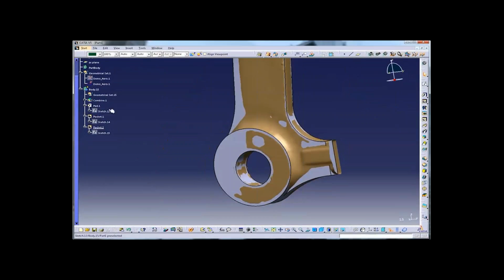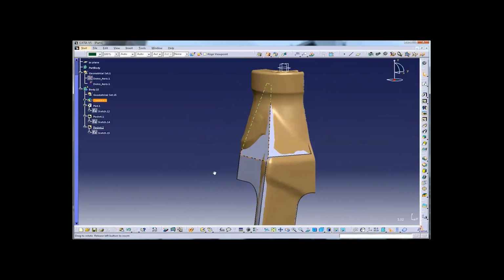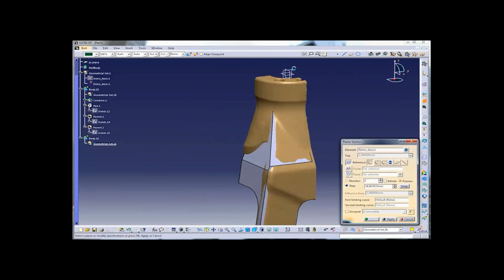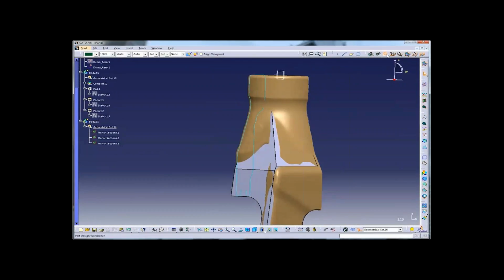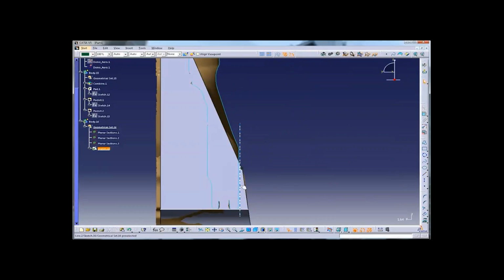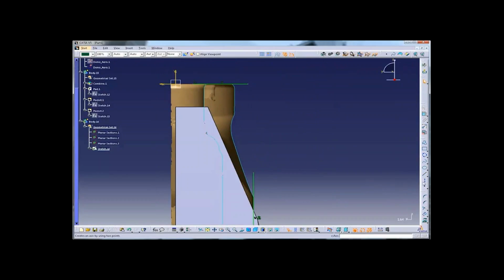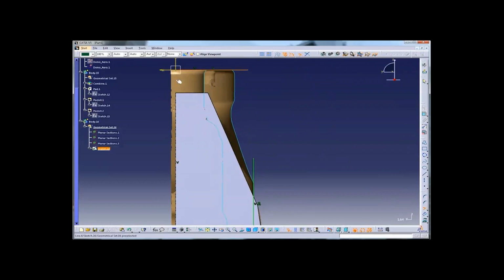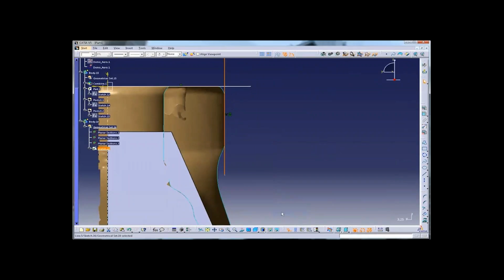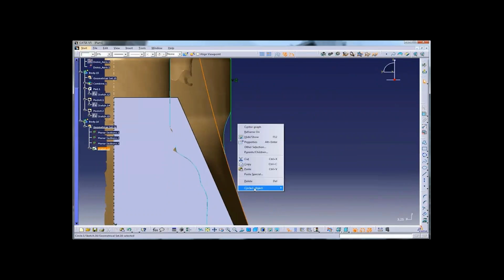I'm going to add a basic small hole there. You could have used the hole function, or here I'm using a pocket, so that's your choice. And at the top, you see here, we do have a revolve feature on the mesh, on our brown scan data. So this is why I'm going to create now a new profile. This time, this profile will be based on a cross-section that you can see in light blue. Again, you could have created points on these cross-sections in order to create more accurate profiles. Here, the design is pretty simple, so I can simply put my lines and arcs and different elements of my sketch, just dragging them like that over my light blue cross-section extracted from our mesh.